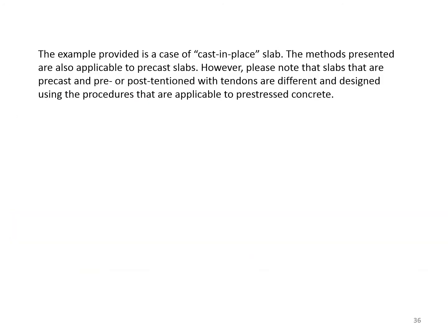The example provided is a case of cast-in-place slab. The methods presented are also applicable to precast slabs. However, please note that the slabs that are precast and pre- or post-tensioned with tendons are different and designed using the procedures that are applicable to pre-stressed concrete.